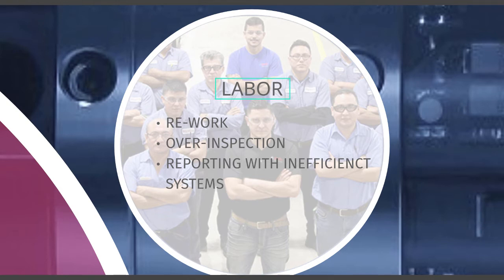So where are wasteful labor costs incurred by you? Rework. Now, not only are you wasting labor expense to have someone rework a part, but you're also adding to the work that your material review board has to do to determine if a part can be reworked or if it needs to be scrapped. Over inspection, right? If you can't statistically prove your process is in control, the only way to know is to inspect your parts. I have a medical device supplier in Minnesota that's contractually obligated to either statistically prove their process is in control or perform 100% inspection.